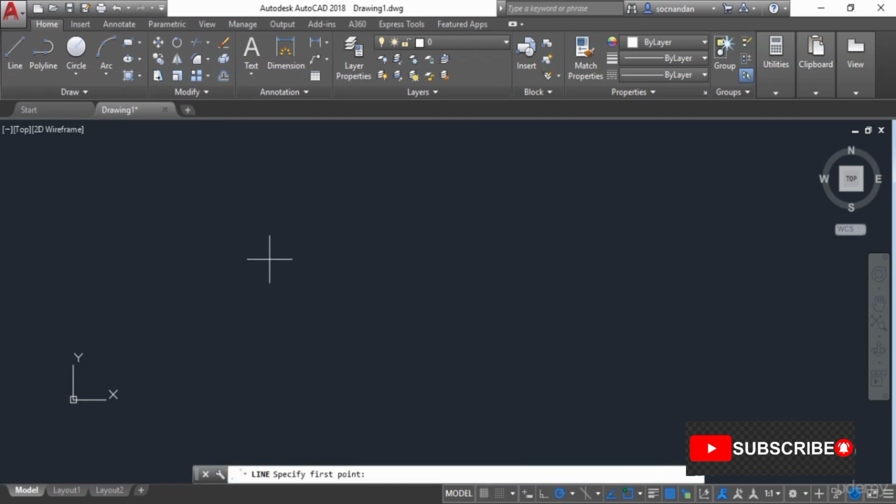Alternatively, you can also use its command equivalent, line, or its command shortcut L, and simply press enter to start the command. So let's type L and press enter, and here also we have this line command. After starting a command, you'll notice that the command line will show in bold letters the name of the command or its command equivalent, and also the instructions that you can follow to make the geometry.